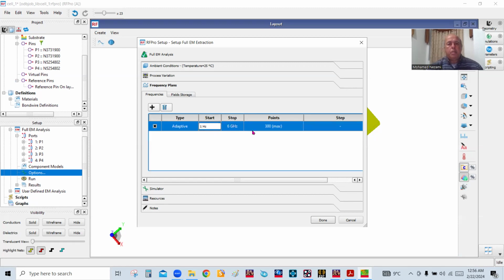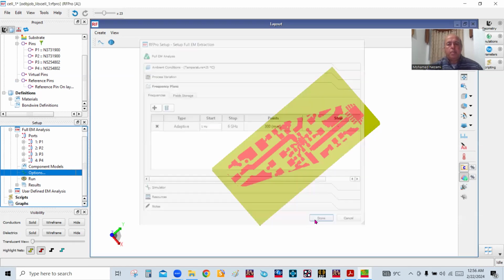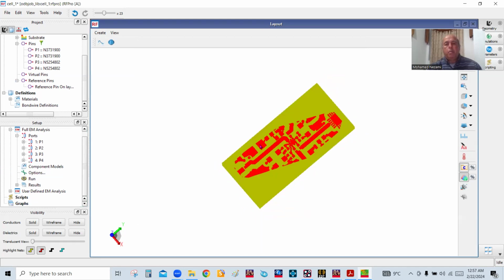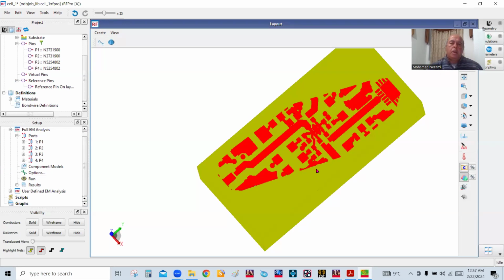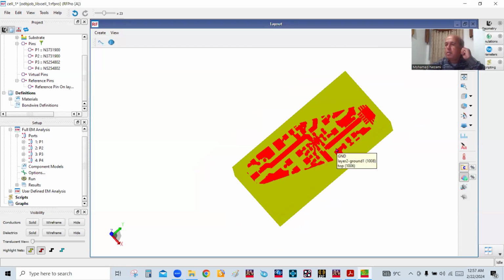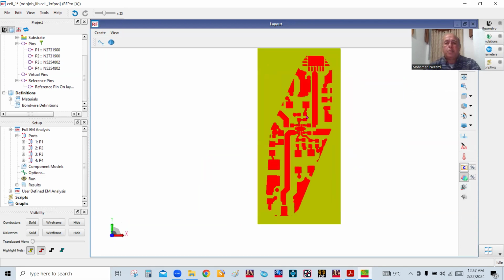Now, this is a Ku band LNB, but these two traces in here have to do with the part that is carrying the local oscillator signal from the phase lock loop module. If you look at that, that's running at S-band, 3 gigahertz.